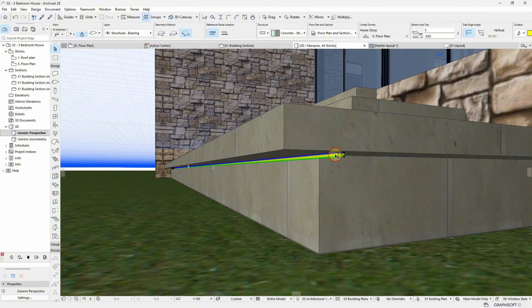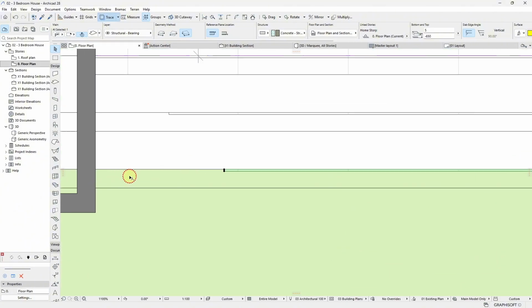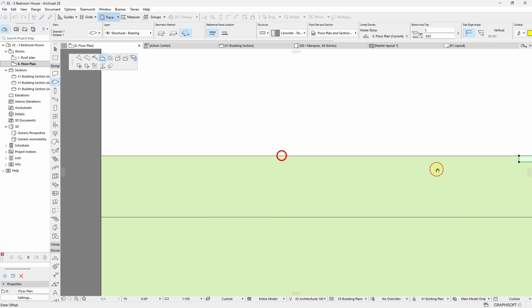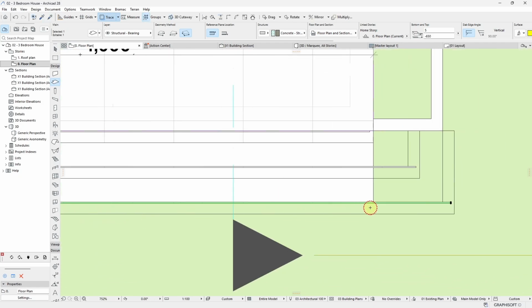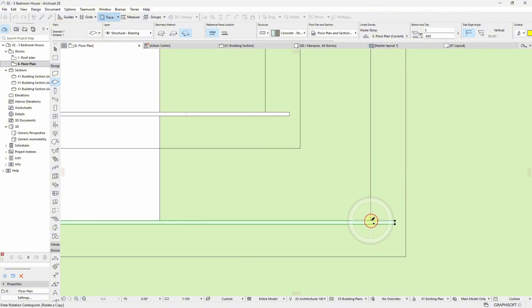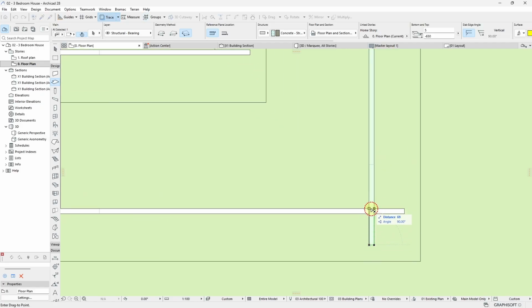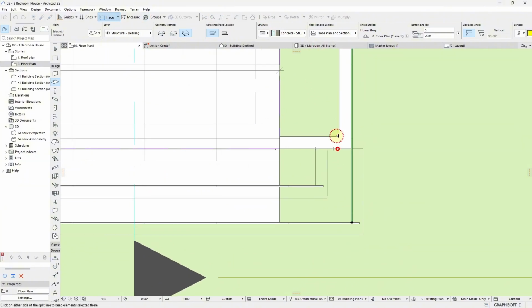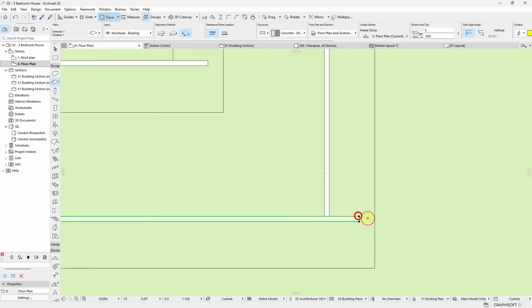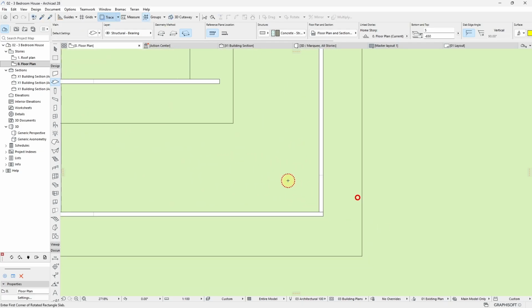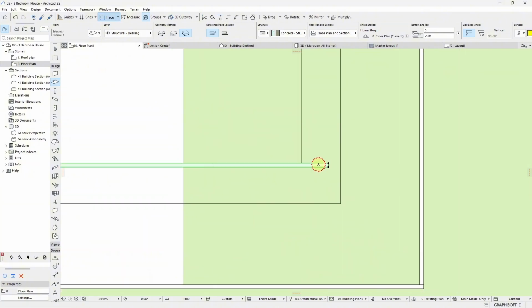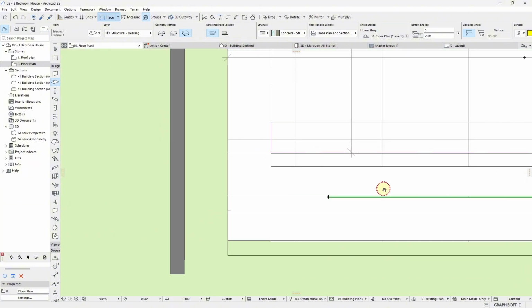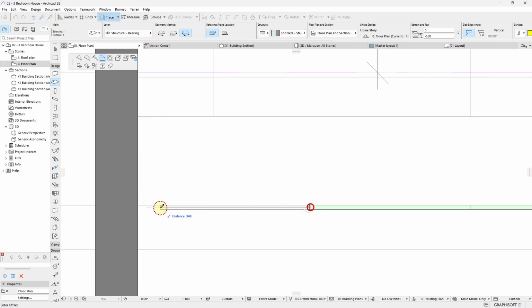So all I just need to do is to adjust it on the floor plan. I select this and increase the length here to touch this wall. Then I do Ctrl-Shift-E, drag, I rotate a copy of this to this, and I move it. I move the end stop to here, and I cut it off from here. So I'm going to come and cut this off from my wall, and I bring this one inwards a little bit to this part. And then I also do the same thing here. I come and I align the edge to the wall.